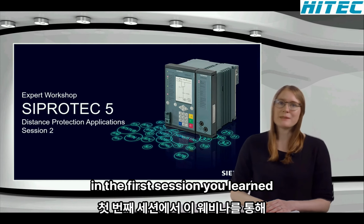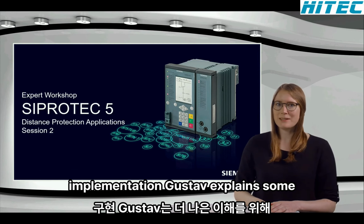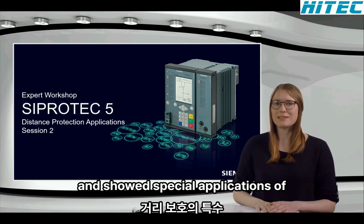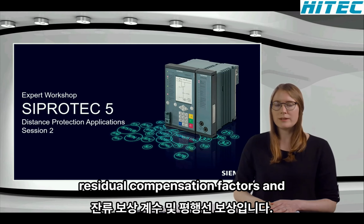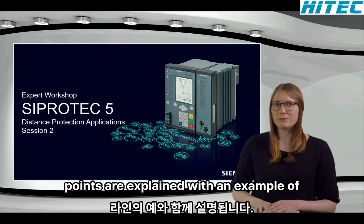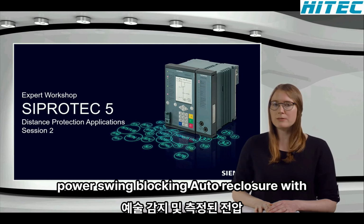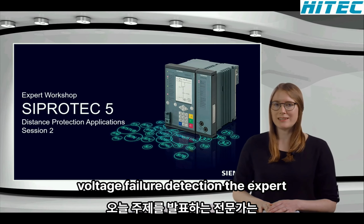In the first session you learned something about the method and implementation. Gustav explained some examples to get a better understanding and showed special applications of distance protection. The topics for today are zone grading, residual compensation factors, and parallel line compensation. These 3 points are explained with an example of an overhead line. Further topics are power swing blocking, outer reclosure with secondary arc detection, and measured voltage failure detection.